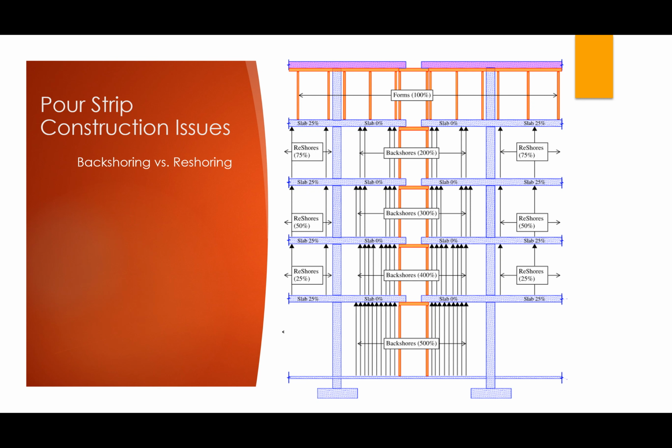What percentage of contractors do you think understand this concept? The difference between backshoring and reshoring and how the load accumulates? I don't think contractors even tend to be very familiar with this. What you absolutely need is a professional structural engineer designing these shores for every building. Because you really need that kind of specialized knowledge to understand the nature of the backshoring here as opposed to the reshoring. Okay, and so this is kind of the critical insight that I wanted us to have when we return to that picture at the very beginning.